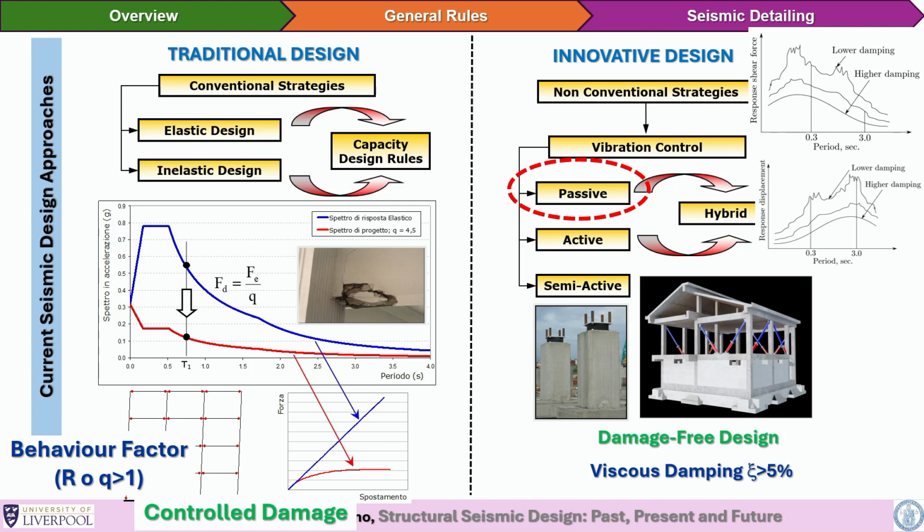And what are the alternatives? These days, we have alternatives, and those are based, for example, on vibration control, something that is not new in engineering but has been taken from mechanical engineering. Even your dishwasher at home relies on this. For example, whoever is experienced with laundry, when you start your washing machine, it starts to rotate, it starts to move, but then suddenly it stops because it has some control of the vibration. In that case, it's a sort of passive device applied on the system, on the centrifuge, which has a piece of concrete, typically, resting on it.